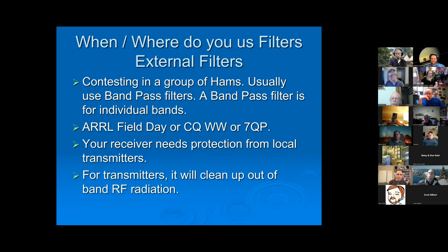So that bandpass filter is going to sit on the front end of your transceiver, and it's only going to allow frequencies in and out of that transceiver that are within that bandpass filter. Very important concept there. But you have to think about it working on both the transmitter and the receiver side.